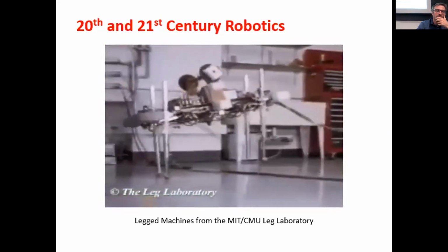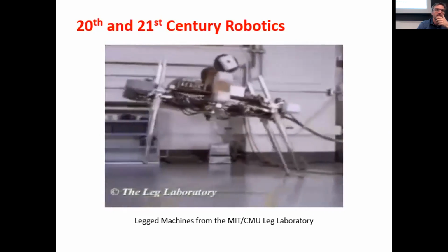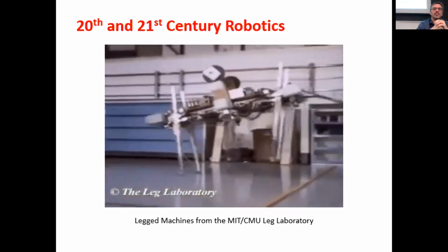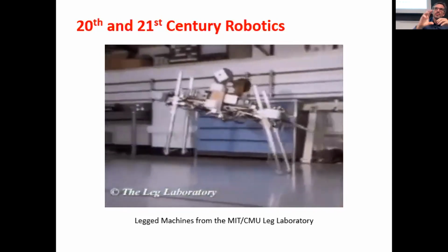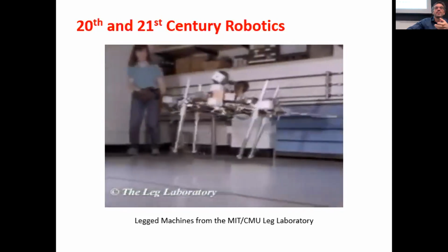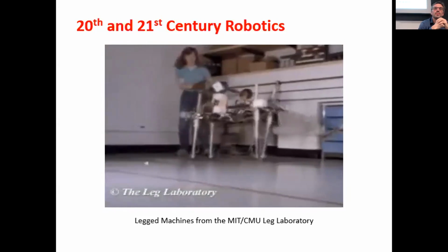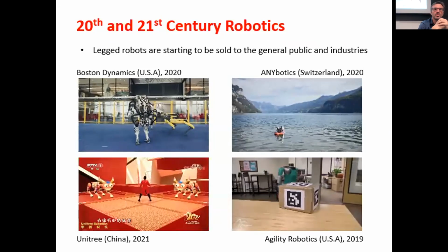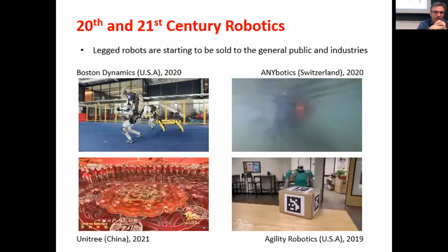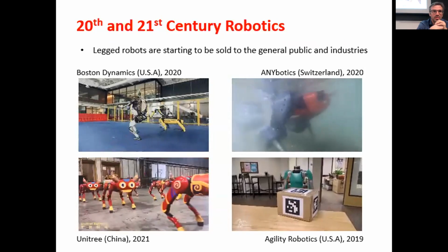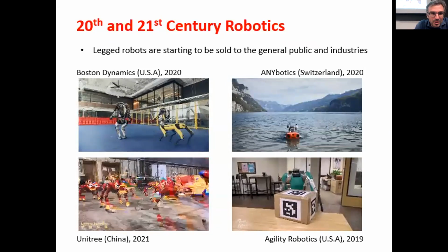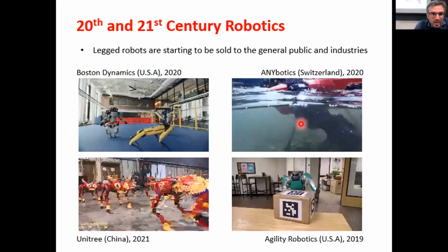And you see here that there are some springs. In this case, these are air springs, so they're air compressed. It's very important for legged robots to damp the contact force. So in legged machines, you need some compliance, some non-stiffness, to be able to avoid big impacts that could destroy the robot.